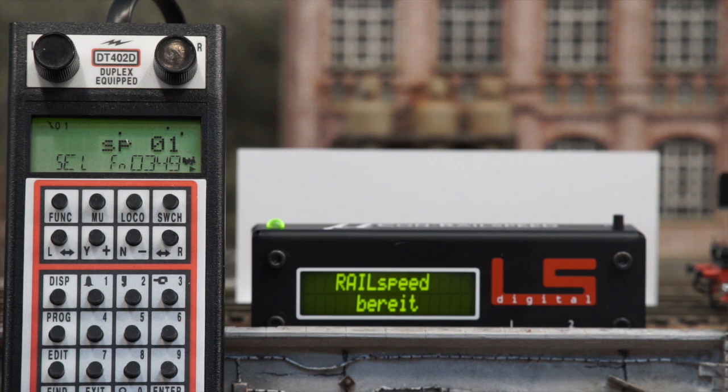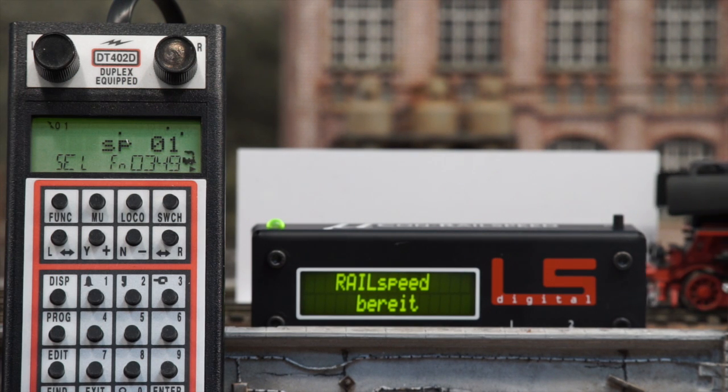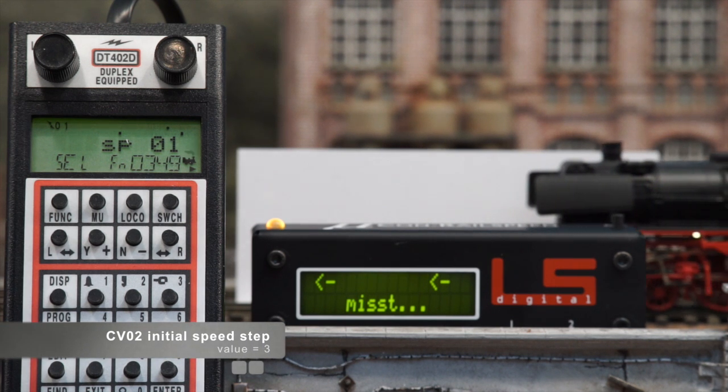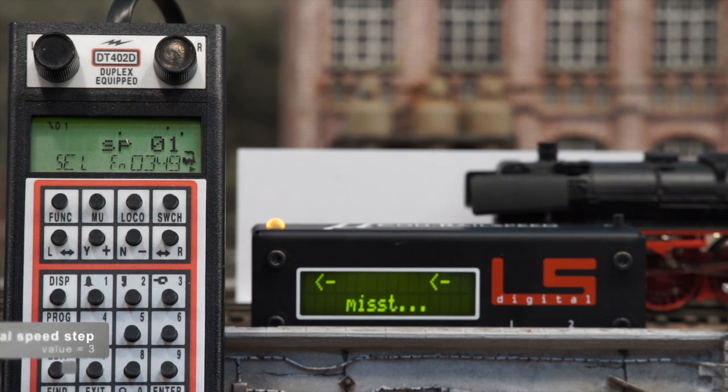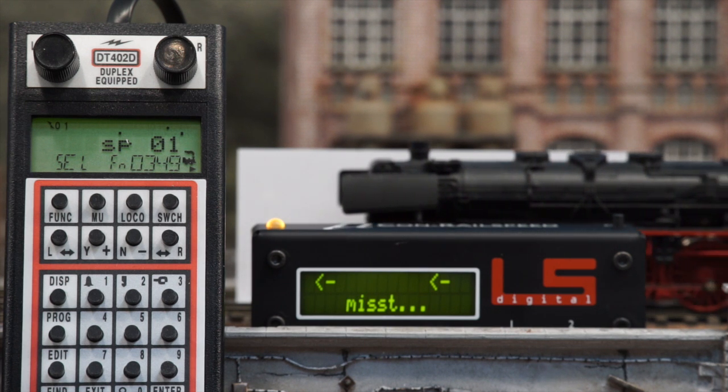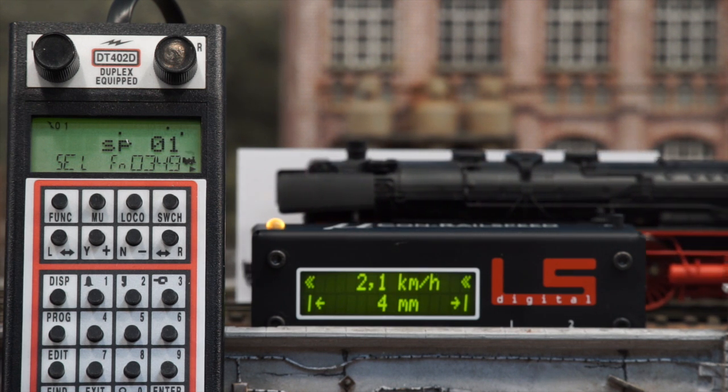Using ops mode programming and a HO scale speedometer from LS Digital, I set CV02 or initial speed step at a level so that the loco is able to crawl at its lowest speed in a smooth manner. Here it results in a scale speed of 2 km per hour.